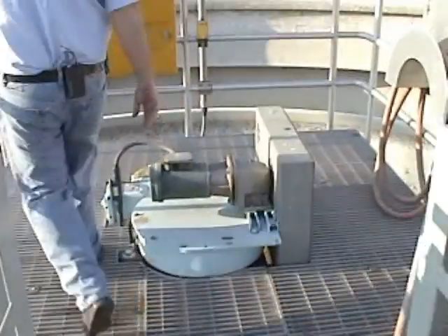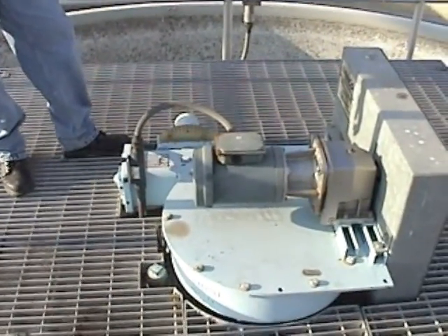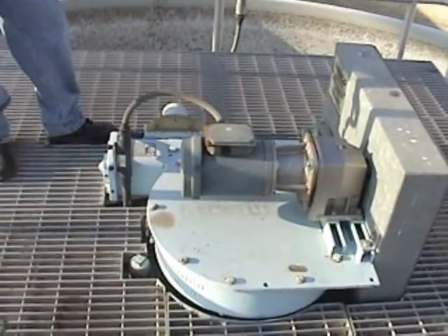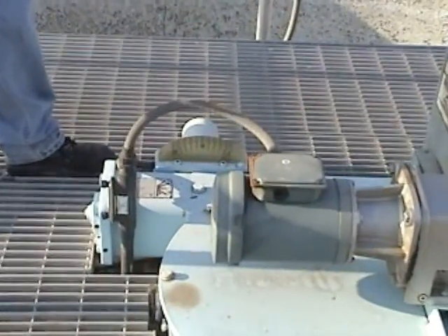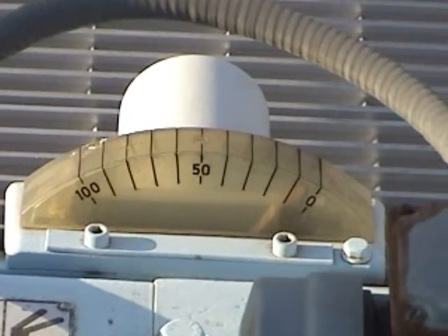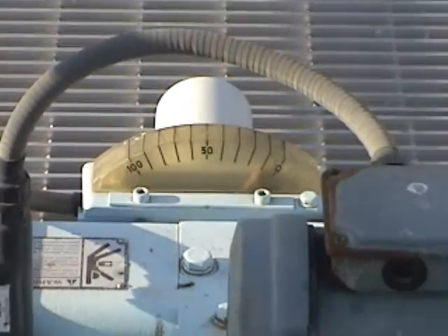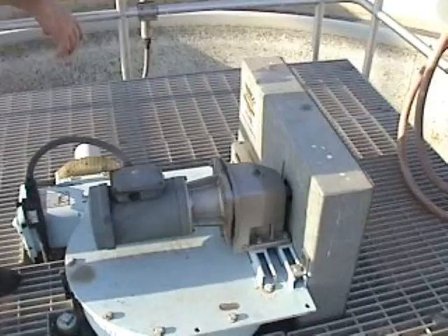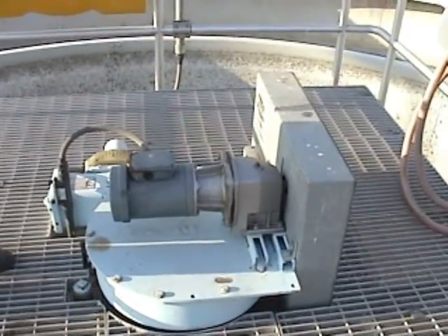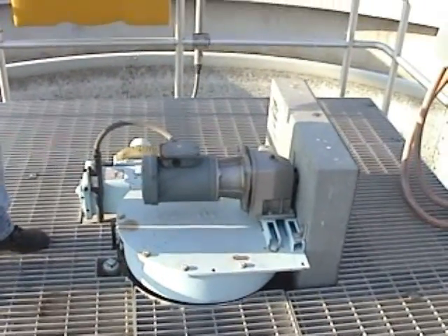This here is the drive for the secondary clarifier, and it does have alarms attached to it. When the drive hits, I want to say 80%, it's measured in torque. When the motor hits like 80% torque, you'll get an alarm, like a priority 2 alarm, saying I've hit high torque. Then at like 90%, you're going to get high-high, so it's telling you it really hit something. There's shear pins in here. If it does hit something really solid, it's going to break a shear pin, which will separate the motor from the drive unit and protect the motor from destroying itself. So the shear pin will break. So you get alarms for high torque, shear pin will break.